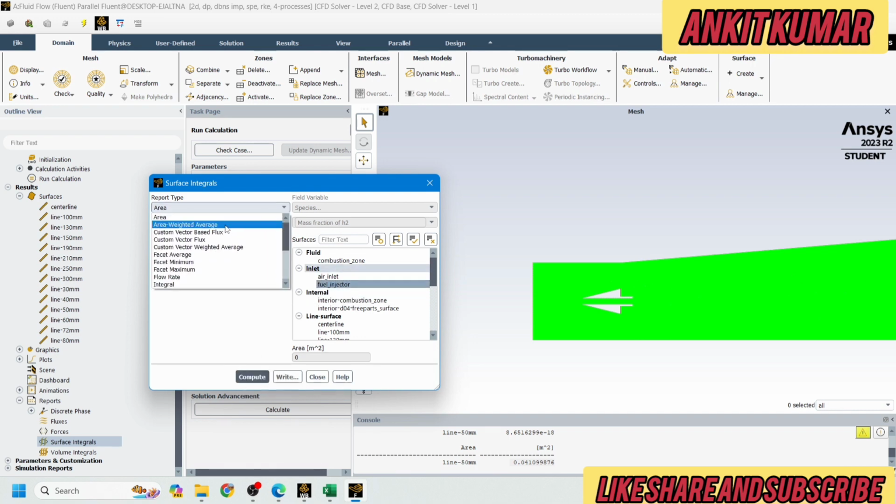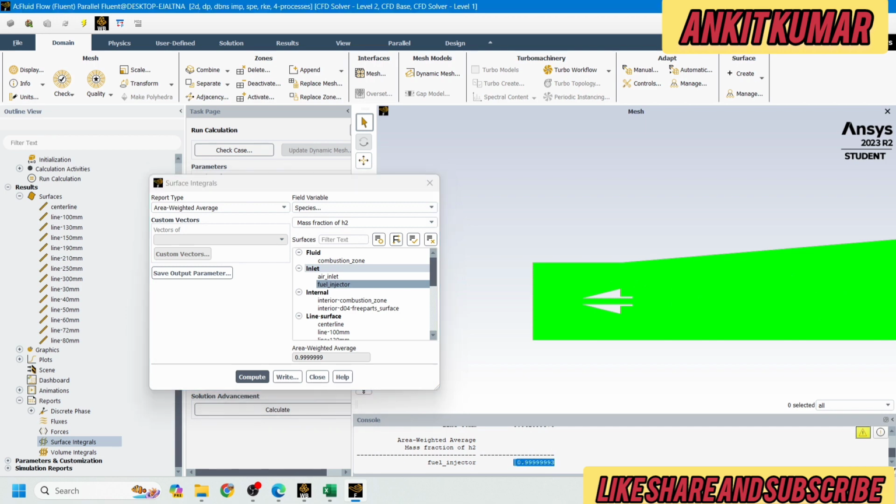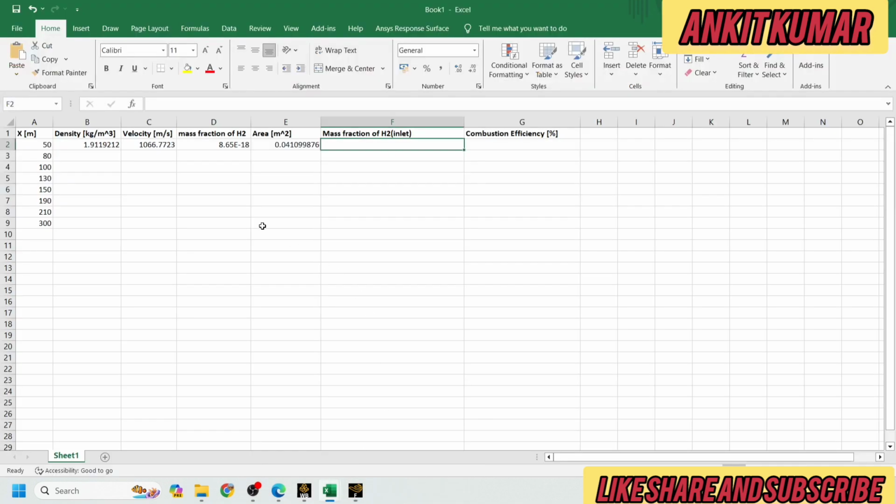Now select area weighted average from report type, and from fuel injector, how much mass fraction of hydrogen is coming out. It will get calculated and displayed. So we will select fuel injector and species, mass fraction of hydrogen, and press compute. This is the mass fraction of hydrogen from the fuel injector. Select this value, press Ctrl C and paste it here.